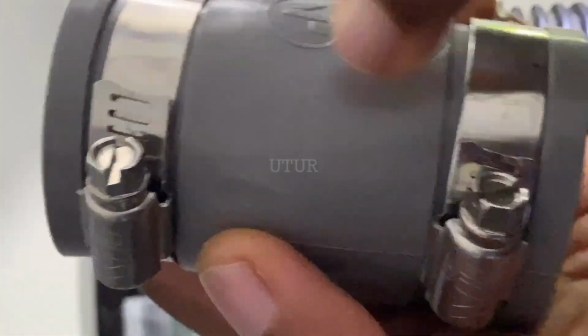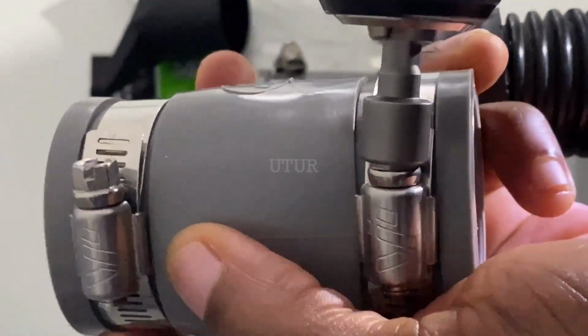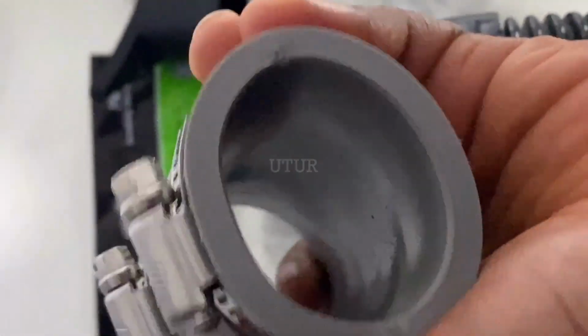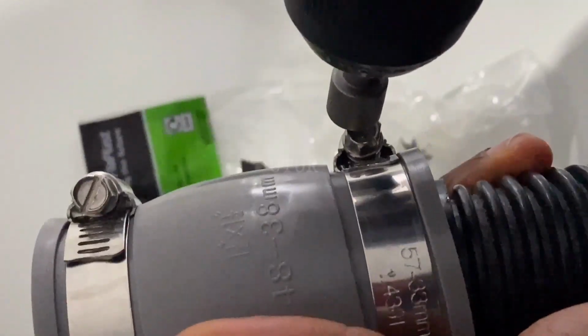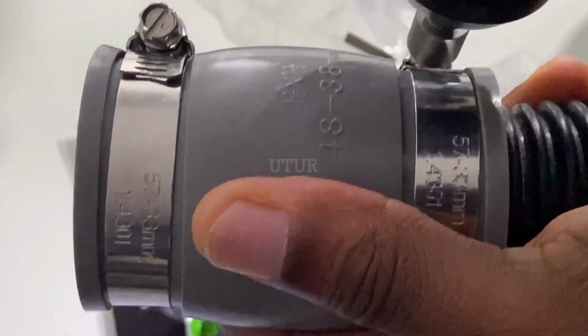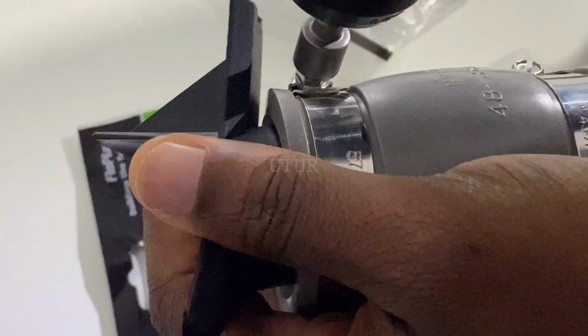So when next your clip teeth fall out of position, don't discard it. This is the way to fix it. Okay. Don't try to push it in. Set it up into position, then torque tighten gradually. Okay. And your clip teeth should come back to full functionality. So here we're replicating the process for the 40mm coupling, and you can see the force of the drill yanking the coupling and the flexible hose away, and that's what we're trying to prevent.